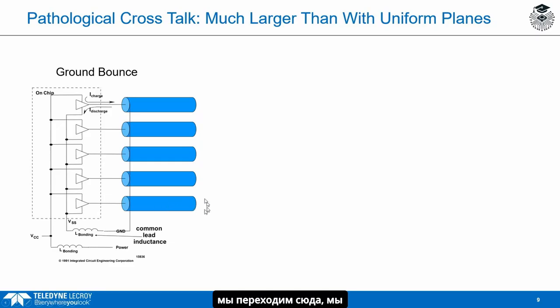And that means that when we go over here, we measure the voltage on this line. We measure the voltage of the signal relative to the local ground on the board, the plane on the board. We're going to see all of these guys generating the ground bounce through this lead. So they're going to generate the dI/dt through that total inductance. We're going to see a voltage on this side compared to this side. This side's tied to ground. We're going to measure that over here. And look on this guy here, we're going to measure the voltage on this point. This entire die, this entire VSS of the distribution on the die is going to bounce relative to the board ground. And we're going to see that as this guy's voltage output.